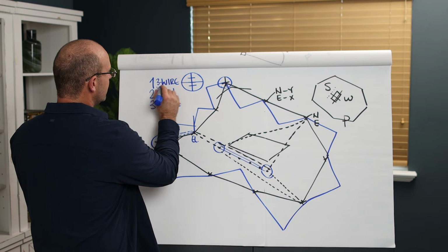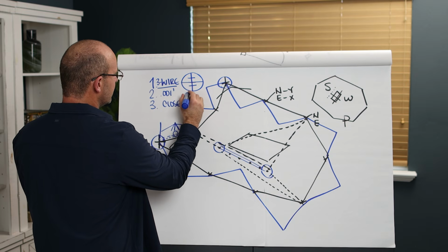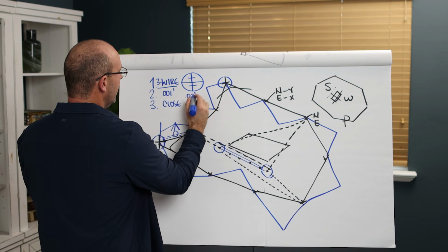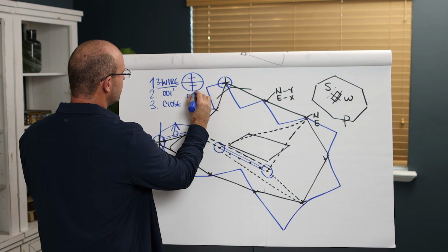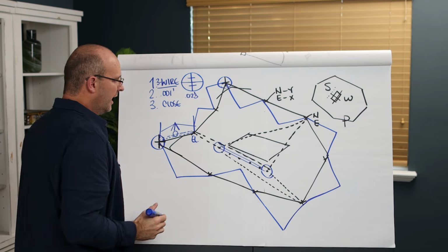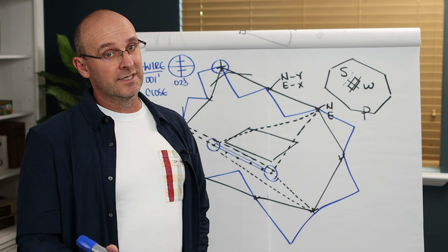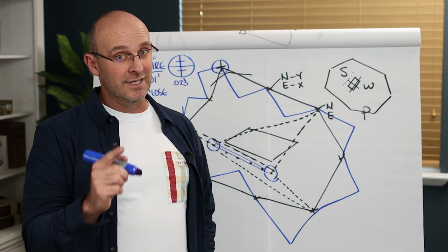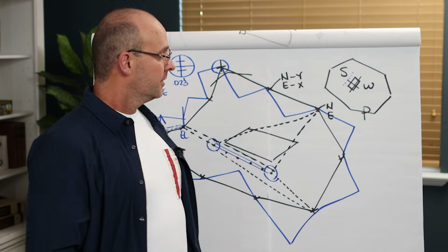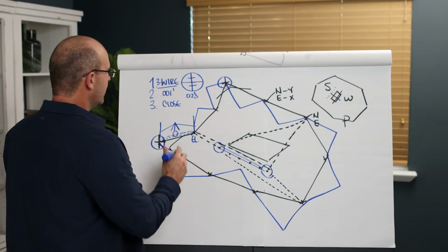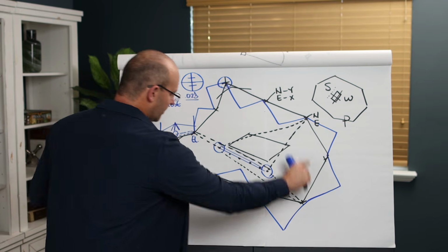The other thing is you're not going to read these to the nearest hundredth. You're not going to be like, okay, 252.02. No, you're going to be like 252.023 feet. And somebody would be like, well, Jason, you're guessing on that third number. But if you round to the nearest hundredth, you're intentionally guessing to the wrong number. So if you guess to the right number, that's much more accurate than rounding. So you're going to estimate to the nearest thousandth and you're going to close back.